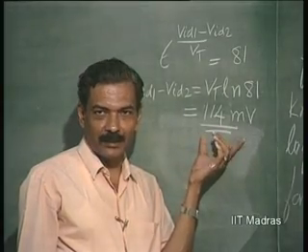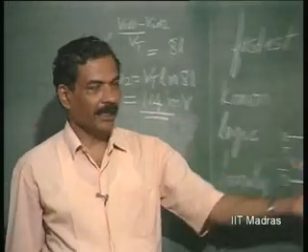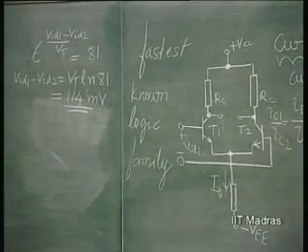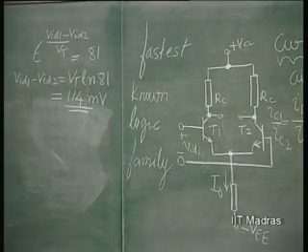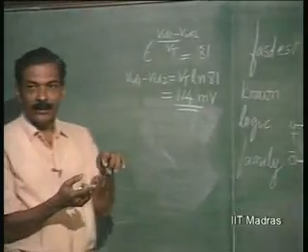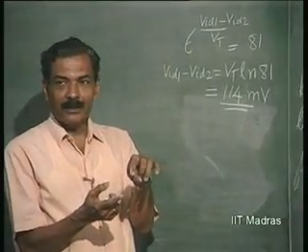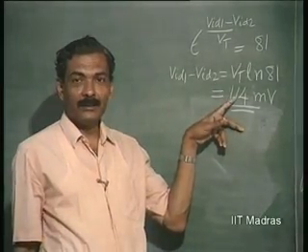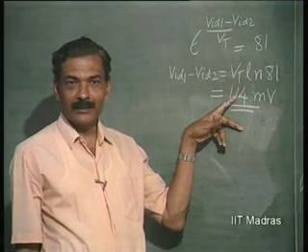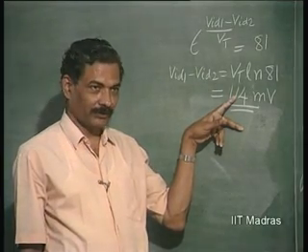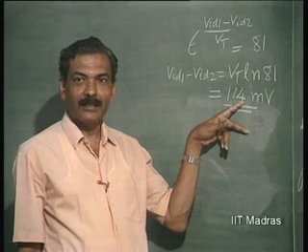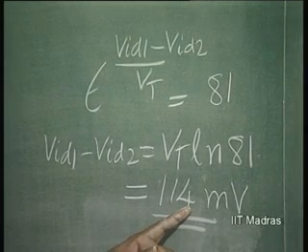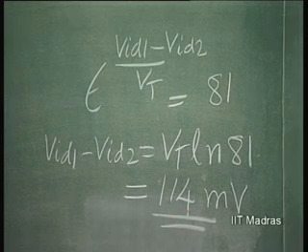Please remember this always, and how it can be derived. So, in the case of emitter coupled logic, you will see that the logic level for 0 to logic level to 1 should only swing from one value to other by an extent of 114 millivolts. Unlike in the case of TTL etc., where the swing is about 5 volts. This is the kind of thing.